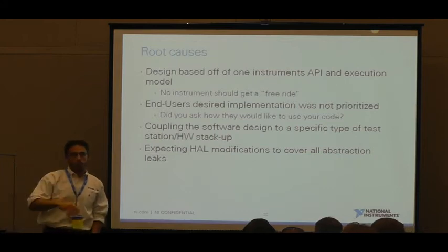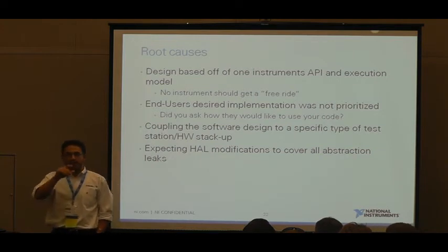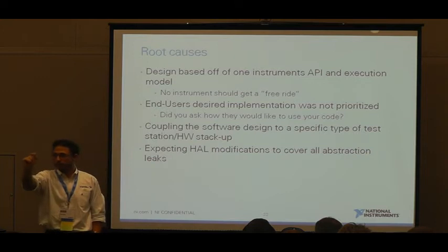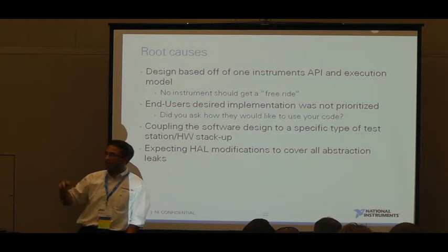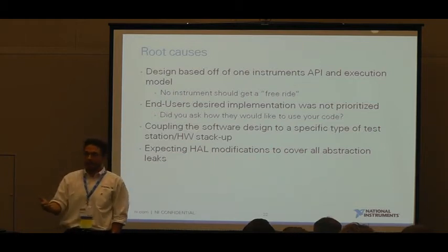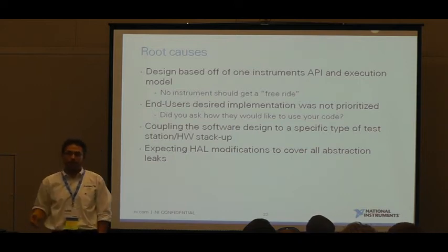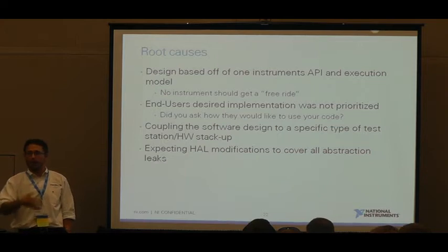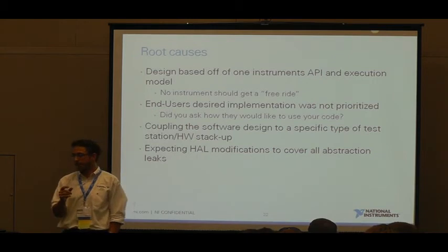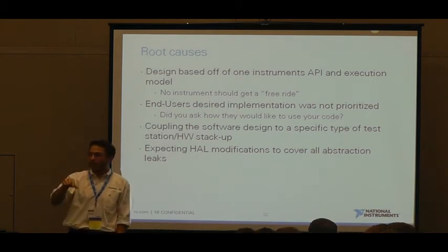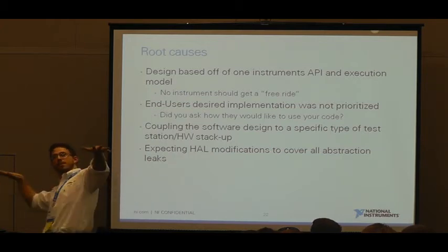So, what are the root causes behind this? Well, the design, as I mentioned: you have one instrument in mind, one instrument flow. That could be because you're not familiar enough with how other instruments of a similar class are talked to, how they behave, things that might be different between an individual instrument and a different instrument. And that's okay. You have a strong desire to create this hardware abstraction, you have to start from somewhere. Hopefully, at the end of this presentation, I'll direct you to a place where we can expand the conversation on that. But the reality is that you've given that one instrument a free ride. That one instrument has just sailed into your hardware abstraction layer without any kind of problem.